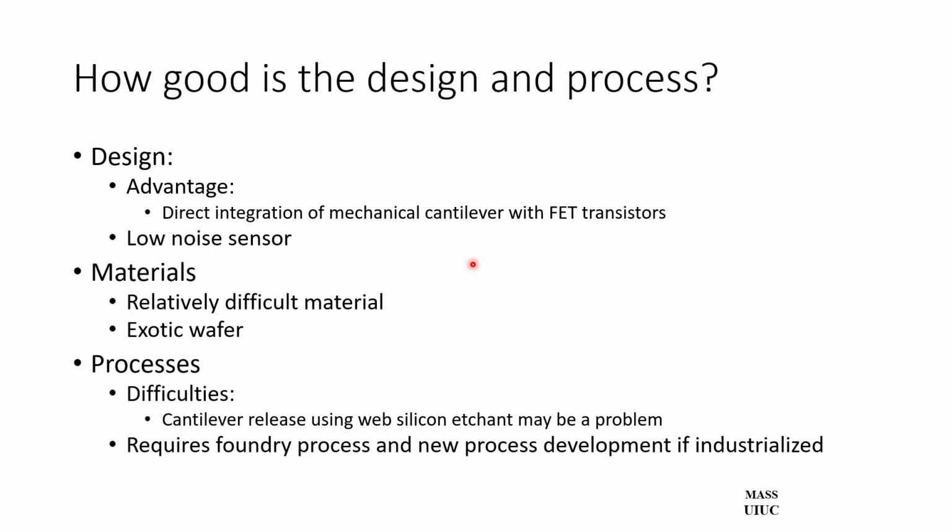In terms of materials, it's relatively exotic, and the wafers are also exotic because you need to grow epitaxy silicon and then later remove it. The process difficulty mainly is the cantilever release using wet silicon etchants. This was not something that's done very commonly.